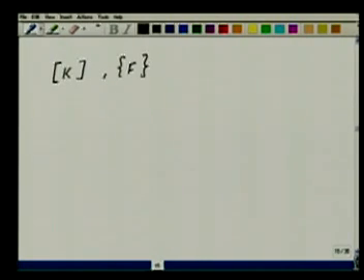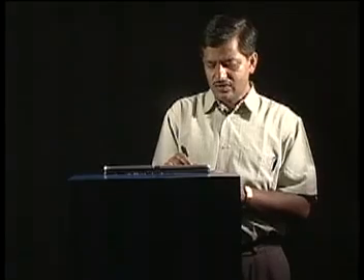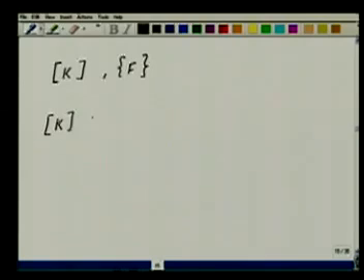And what we have done is we have done the integrations over these elements. Now we have to add them together to form the global entry. So tell me, for the 6 element mesh that we have taken, for the 5 element mesh, so let's say n is equal to 5, and also let us assume that all the elements are of the same size. That is, it's a uniform mesh. That is, hi is equal to h is equal to L by n. Let us take this particular case.